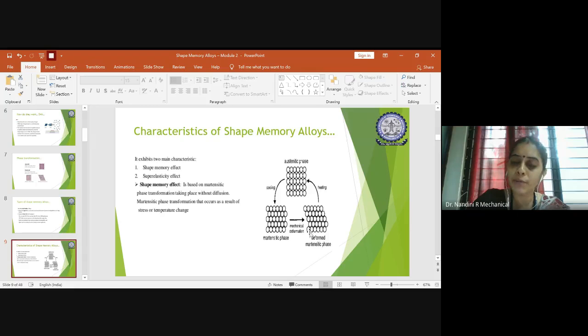So a minor change in the memory will come back, but you can say that around 90 to 95% of the memory can be regained by the cooling treatment. I told you initially also, it won't come back to 100% of its geometry, nearly 90 plus. So it depends again upon the combination of alloys you are using and for which specific application. So this will be the entire cycle of the shape memory alloys, showing the behavior related to the shape memory effect.